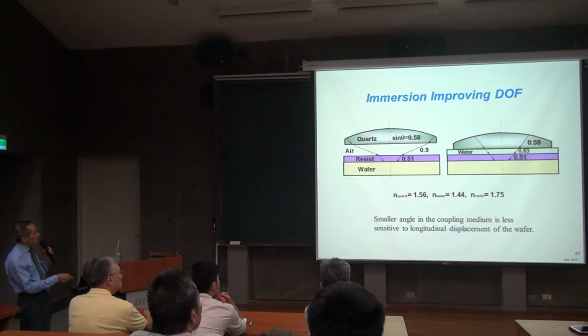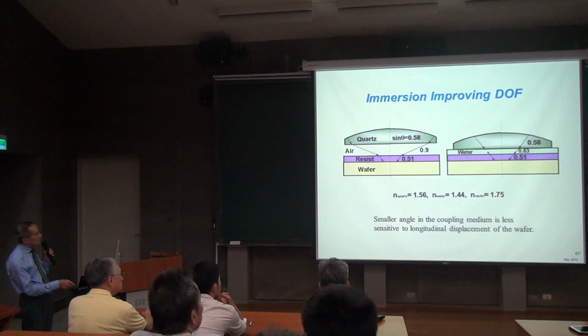And depth of focus is the same thing. I'm keeping the same resolution at 0.58, but now this angle is very steep, and this angle is less steep. I end up with more tolerance of the thickness change here, so I have better depth of focus.